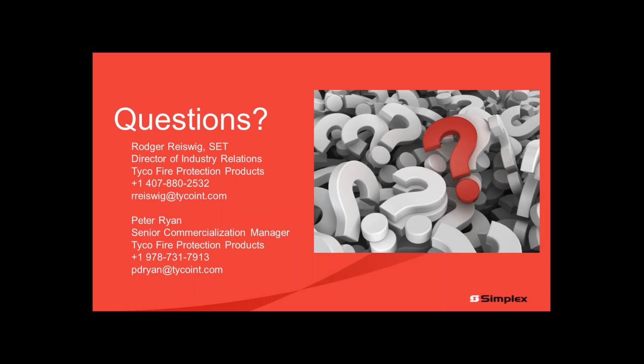Just out of curiosity, for an environment like that, would there be any applicability or potential for using either a heat detector or a heat detector in combination with a CO base? Yeah, if we don't have too much of a worry on the material itself, like if it's a paper mill and we've got a lot of dust of little pulp of paper going through, and it really is just the steam that we need to overcome, then I would definitely look at maybe heat detection or a combination where we have heat detectors and carbon monoxide. Carbon monoxide is unburned fuel, so if we know that we have a little bit of unburned fuel in the air and it's over a certain temperature, it must be a fire, and we'll go into alarm based on that.